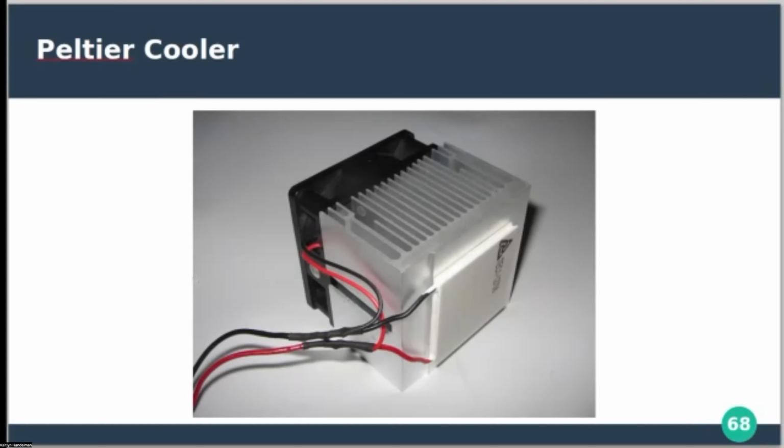And you can use that. If you cool off the hot side, you can get the cool side to be really, really cold. Sometimes you also see these in the little fountains where you get cool drinking water. Sometimes they'll use these Peltier coolers. They're not very efficient, but they're small and compact, and they work on thermoelectric principles.